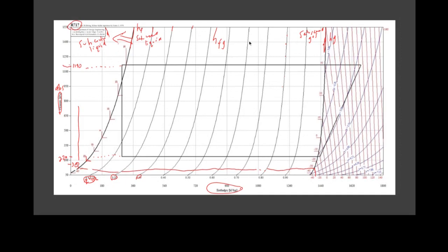So down here, we've got subcooled liquid. Anywhere in between those two lines, we've got two-phase mixture. And by two-phase mixture, what we have is both liquid and gas coexisting, just like with steam. And then when we get above the saturated gas line, everything here is now superheated. And I know, we tend to think of superheated as being, oh, really, really hot. Well, we can have superheated vapor in a refrigeration system that's 0 degrees Celsius. We can also have superheated vapor that's 140 degrees Celsius.